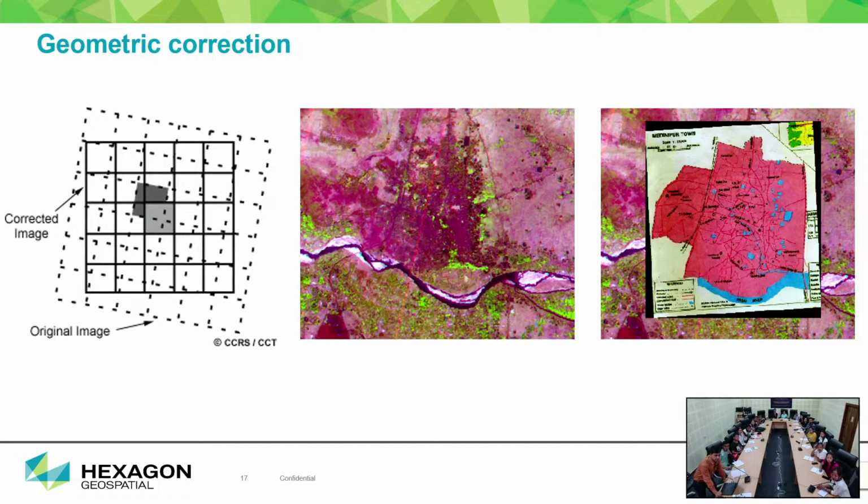We have a satellite image from the Thematic Mapper, and this satellite imagery already comes with some georeferencing information. I am trying to superimpose one of the paper maps, and using the coordinates of this Thematic Mapper I have georeferenced this paper map. That's why I am able to show you this paper map superimposed on the satellite imagery data. So why do we do this?